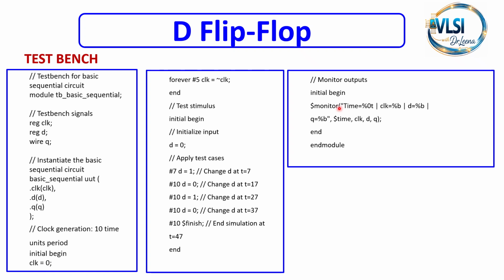Next, we are going for this monitor block. This is for continuously printing time and signal values during simulation. And then we are ending the module. So this is the test bench of the D flip-flop.